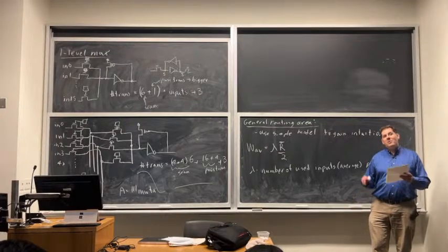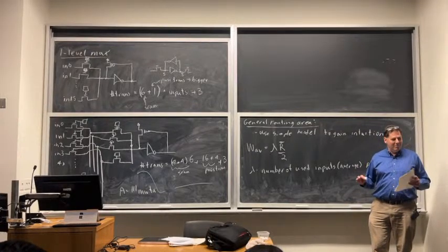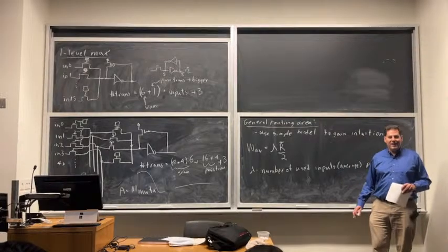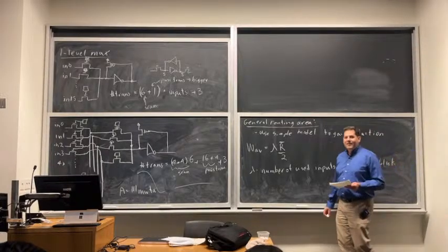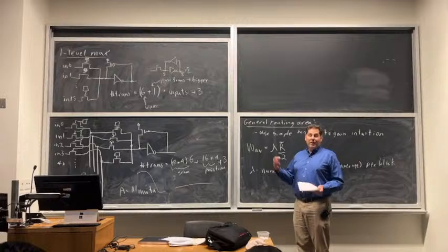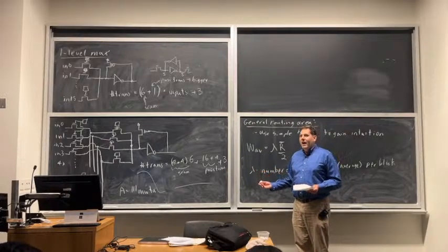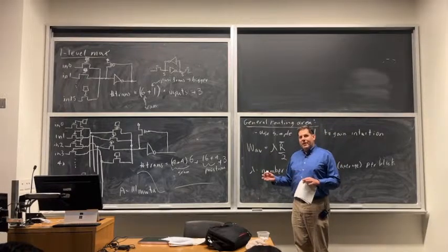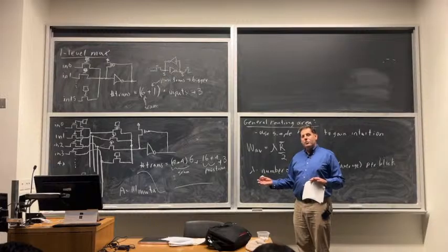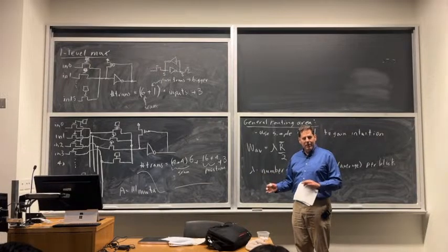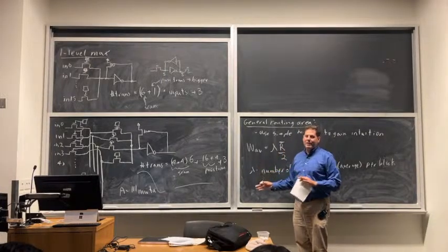So you might be going, this sounds like a really easy question. Maybe it's a trap. It's not really a trap. If you go, that sounds obvious, go for it. So you think 4? Yeah, it's not going to be more than 4. Synthesis tools can't always use all the inputs on a lookup table. So for sure, it won't be any more than 4. In practice, it'll be a little bit less.